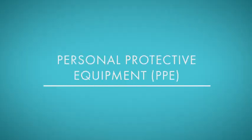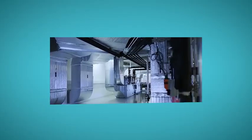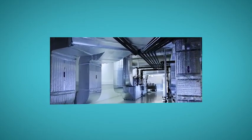The final, kind of the least effective method of control is what's considered the use of personal protective equipment, or PPE. So an example of that would be, say you're in a dusty environment, instead of installing a ventilation system, you say, okay, we're just going to put like a filtering face piece or respirator on the people who work in this environment. And in those examples, you're really relying on the effectiveness of the PPE and also the training that you provide the workers to use the PPE appropriately.